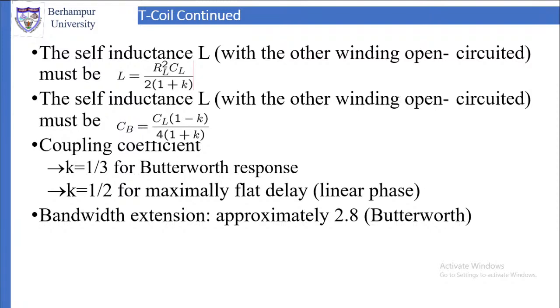Maximally flat means it remains flat over the operating bandwidth. The response will not change, it will not increase or decrease. It will remain almost flat. So if it remains flat most of the time within the operating bandwidth, which means it is a straight line parallel to the frequency axis, then it is called maximally flat.